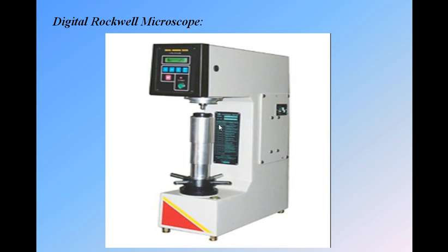And here we have a chart. This chart shows which type of tool you want to use to measure the hardness. We have a diamond tool to measure the hardness, and we have a ball indenter to measure the hardness. Which type of tool you must use is given in this chart. Which tool you are going to use depends on what type of material you are going to use for the hardness measurement. If you are going to measure the hardness of cast iron, you must use the diamond type indenter. If you are measuring the hardness of mild steel, aluminium, copper, then you go for the ball type indenter.